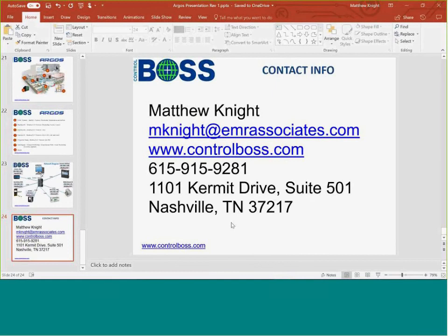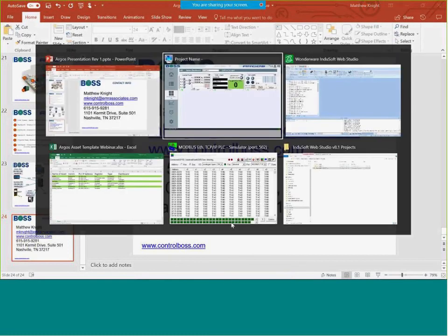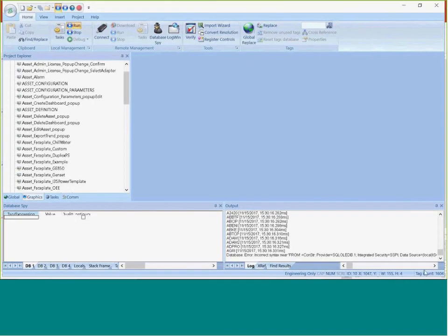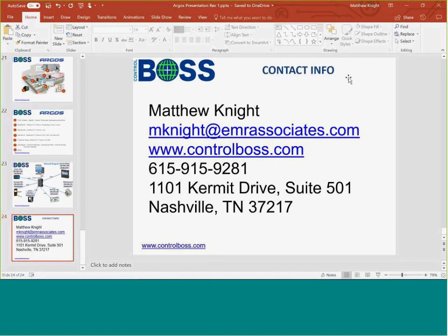Yeah, so because the system's based on InduSoft, when we use a tag, it counts towards the tag count. We have about 800 tags that are base to Argos. With the template, to be able to create things on the fly, to have all the little niceties that we have in there, those take up tags.